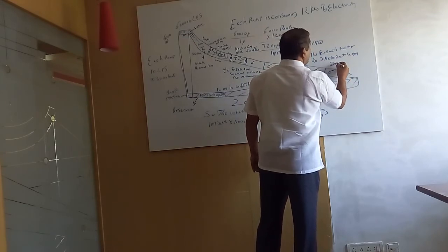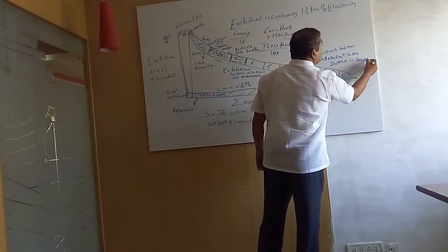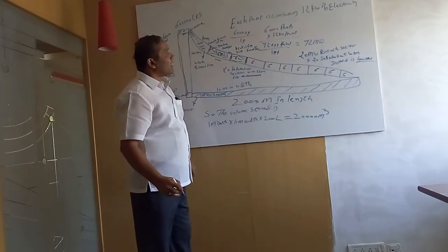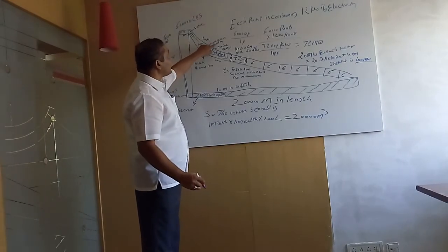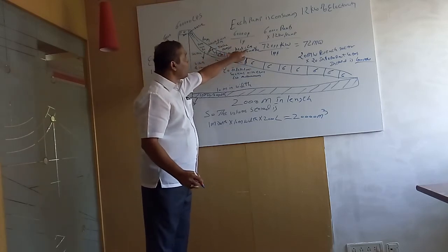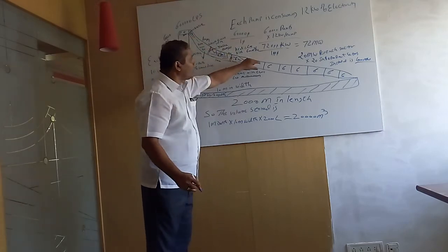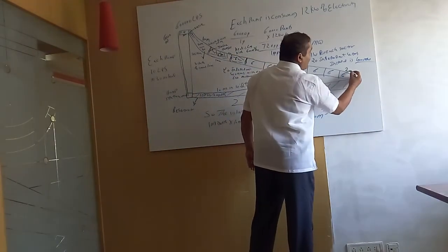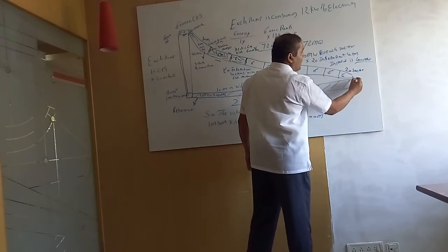Thereby the installed capacity is 400 megawatts. So in this way, in the canal, we are having 400 megawatts, because every sector is opening up 600 meter cube per second. The 600 discharge is common, the 6 meter head is common. So when we are making the water flow from first, second, third, fourth, 5, 6, thereby 20th one, the 20th sector will discharge the water inside the bottom side reservoir.